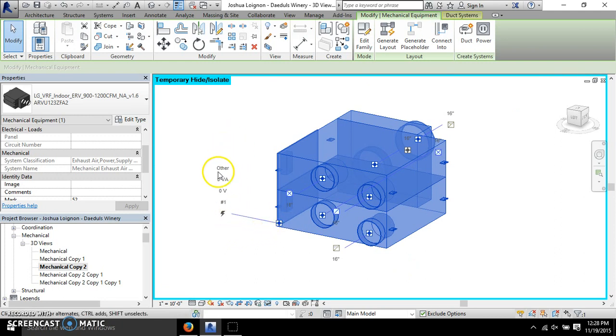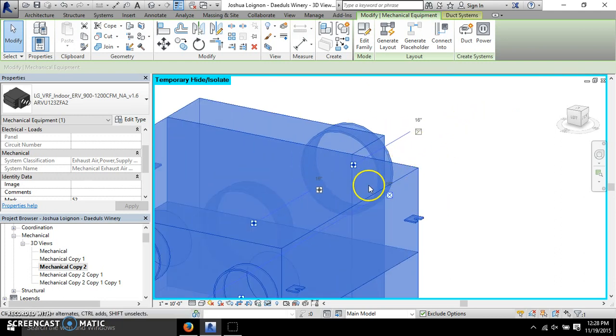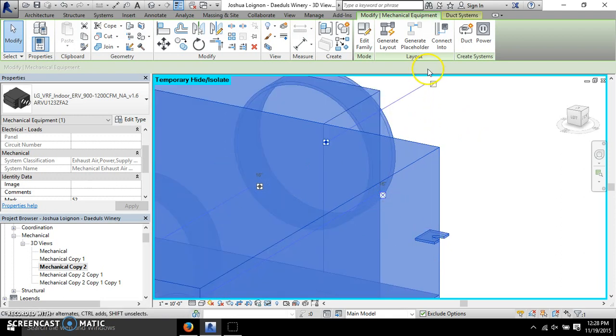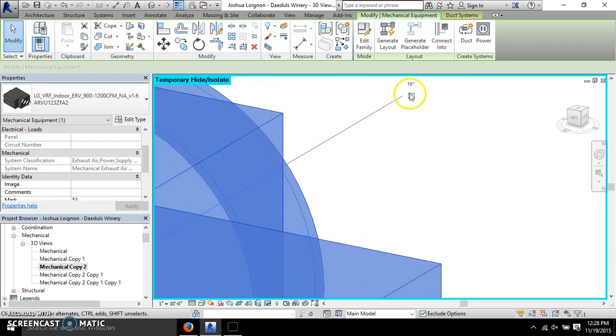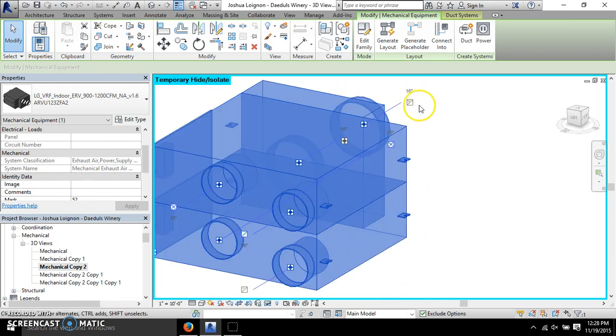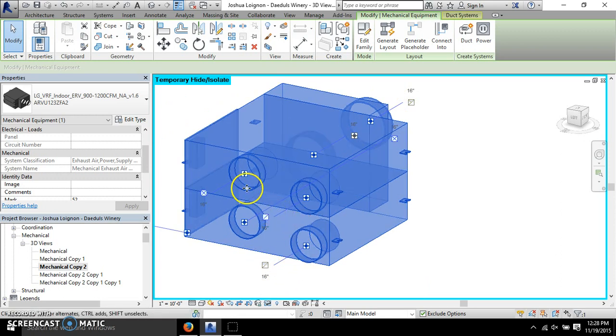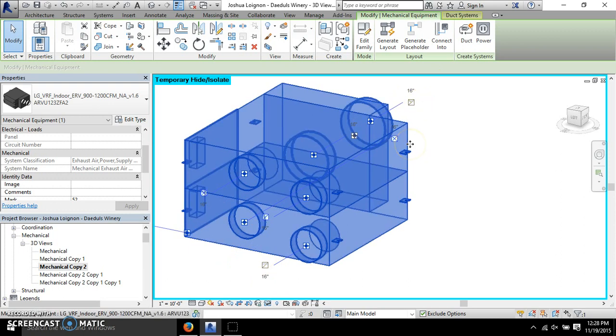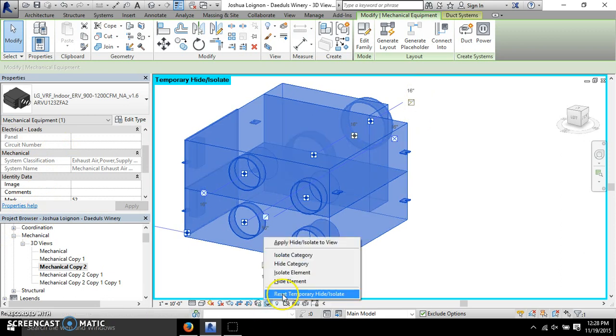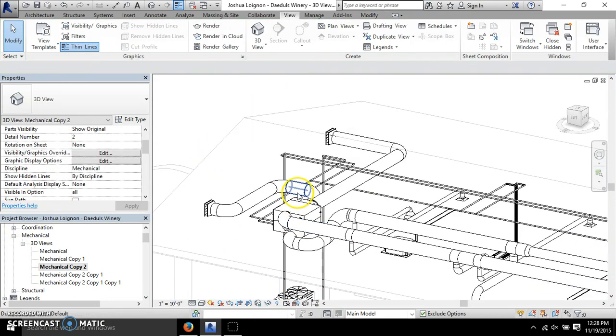And then this is for electricity, if you want to run electricity lines. And then on this side, you have return and supply. So X is a supply, and this one looks like a little line, but it's not a full X through it. So that symbol is always return, and the X is always supply. But unfortunately, Revit only knows it as supply and return. It doesn't differentiate between exhaust and outside air intake, and that's why it messes with your system a little bit if you're trying to do color for the ductwork.